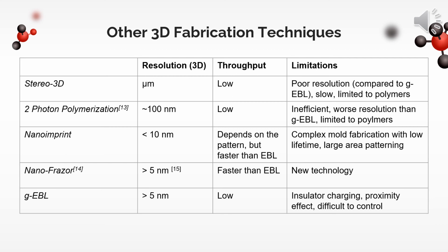Nano-imprint lithography is a mechanical method for nanoscale feature patterning by using a mold. This technique provides elite resolution, demonstrating feature sizes below 10 nanometers. Though this technique can be used to mold very small nanostructures, it often requires EBL patterning for mold fabrication, which can take months. Mold fabrication can become very tedious and may have a short lifetime. Also, it isn't a great method for producing large area devices, but neither is EBL.